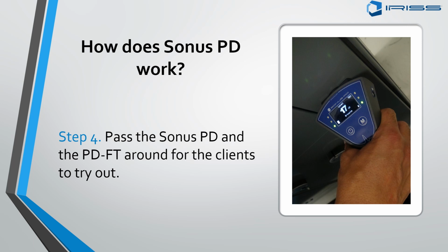Now, what you can also do to test it is you can hold that hockey puck tester up on the gear, a couple feet away, and you will see that as you get closer with the handheld sensor to that unit, it's going to read higher and higher levels of transient earth voltage. So it's sort of showing you, hey, when you have a transient earth voltage event going on, it's inducing voltages in the skin of my equipment. As I get closer to the source of it, I'm going to see higher and higher levels of decibels as a result of getting in close proximity to the source of the fault in the first place.